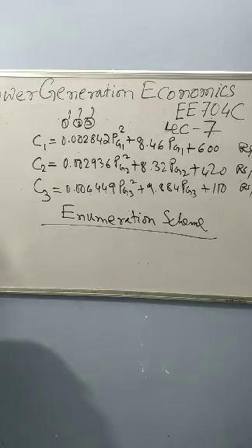This load is divided optimally among the units of each combination by the use of coordination equations so as to find the most economical cost of the combination. Then the combination that has the least operating cost among all these is determined.